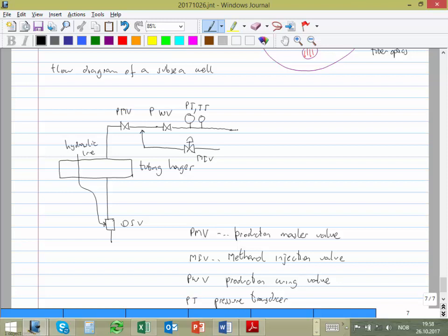But the choke usually is something that you saw from the picture. It's something that has very small holes and very high velocities. So, what is the problem with that? That we saw just already yesterday, that you can have erosion, okay, in these holes. So it's something that eventually I might have to change many times during the life of the well. Okay. So what I do, I put the choke in a separate module such that I don't have to mess up with this one. I don't have to change that in the tree.